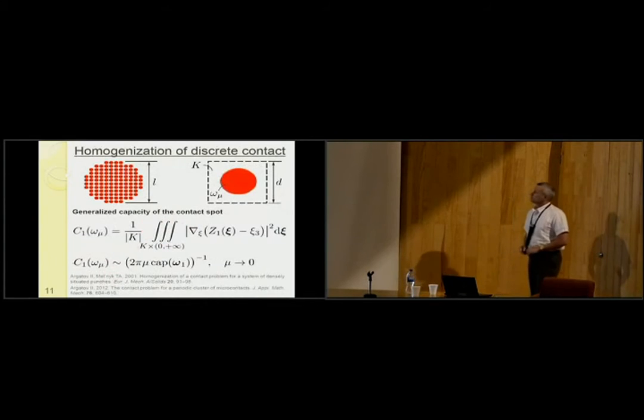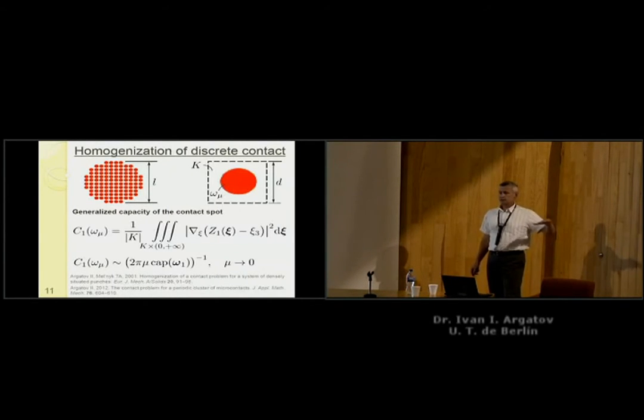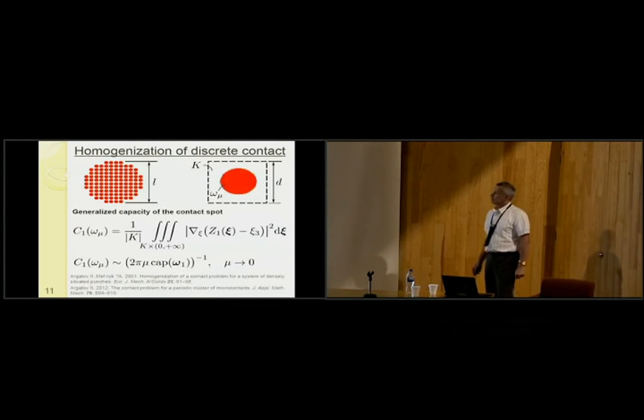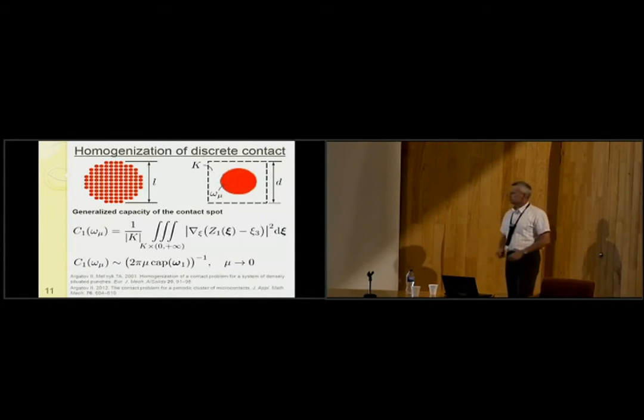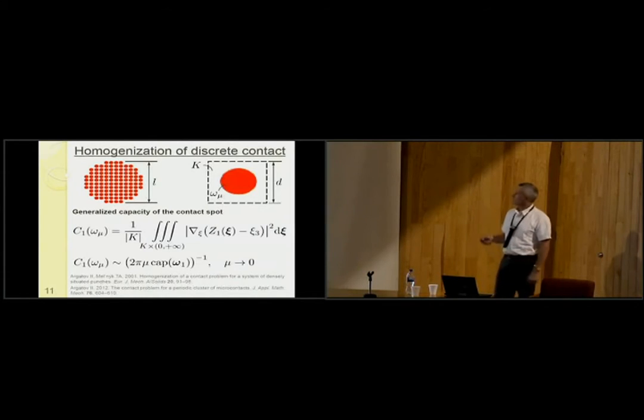So, if we consider a cluster of microcontacts, assuming for the simplicity that all asperities are located on the same level, we can apply homogenization method. And the corresponding solution was developed in collaboration with Professor Taras Melnik from Ukraine. And this problem,